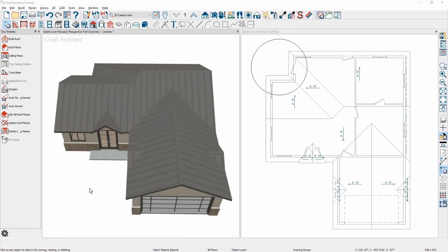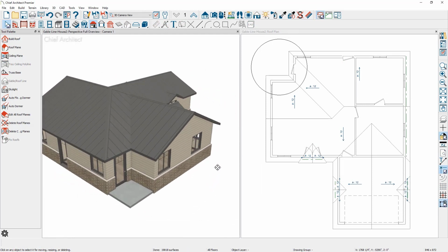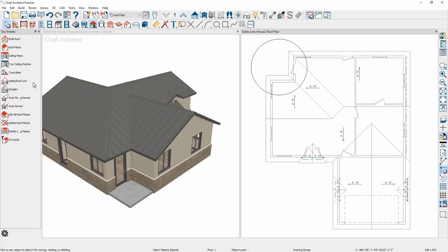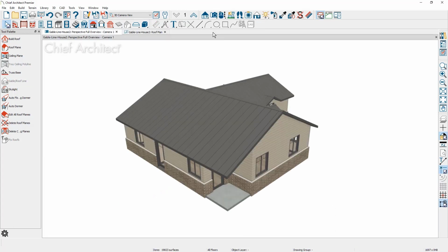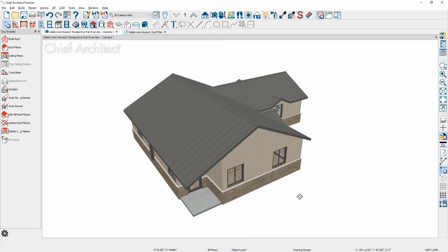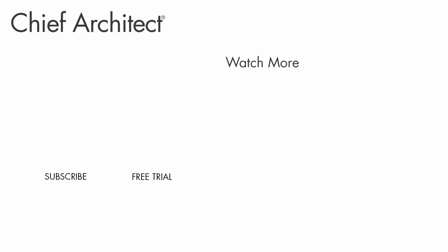The gable roof line can be used in situations where you want to extend the roof over areas without walls. In this example, I have a small entry area. Typically, I might enclose this area with a deck edge or an invisible exterior wall. Another method is to use the gable roof line and enclose the corner. With the automatic roofs on, the program will generate and extend the roof over this area. Using the Gable Roof Line tool is a great way to generate gables and roofs for specific areas of your design work.